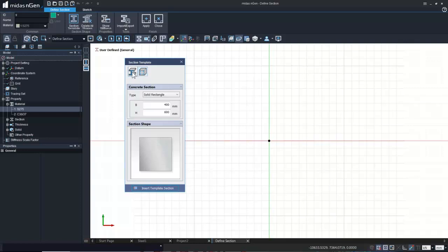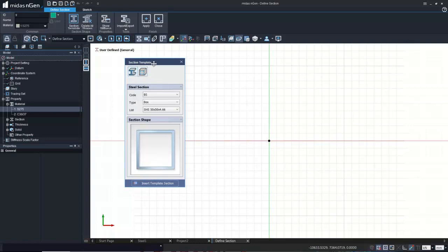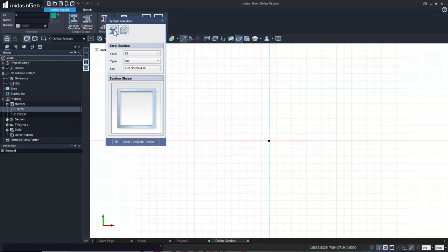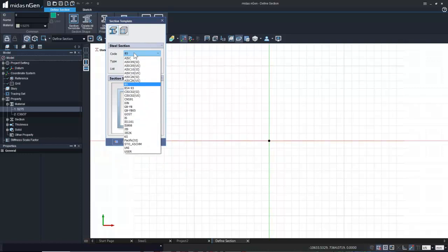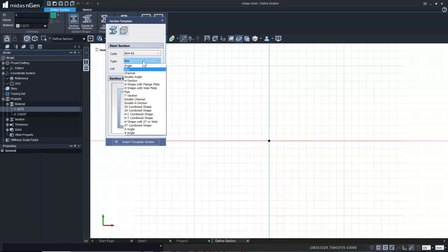Alright, so let me go ahead now with the predefined section properties as per the standard in use. We can see over here there is American standard, British standard, and we have Indian standard as well. If you're using any of these standards, you can easily select and then select the type, like H section, that is the I section actually.